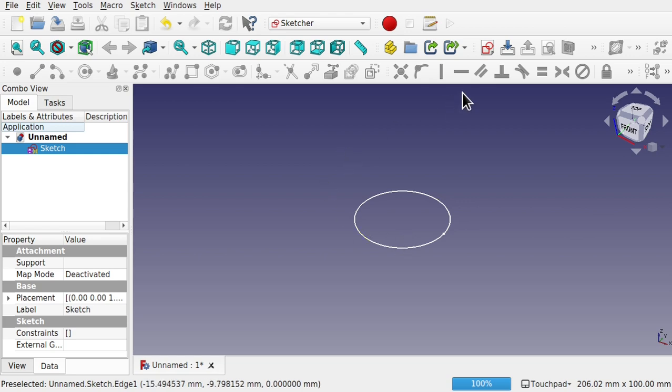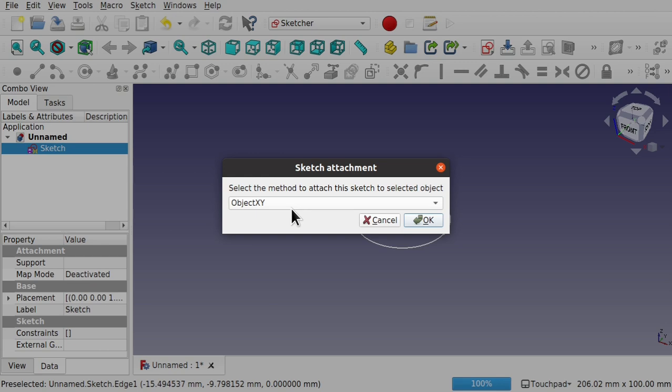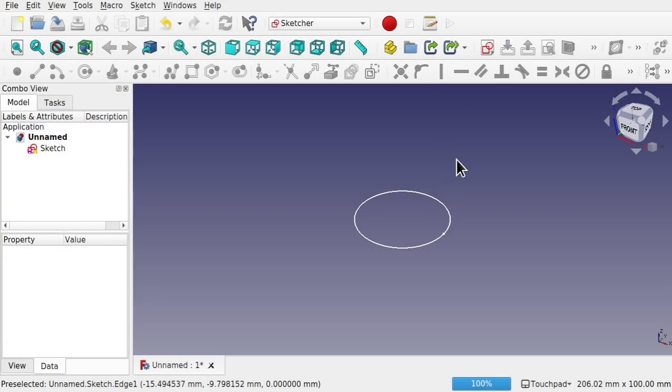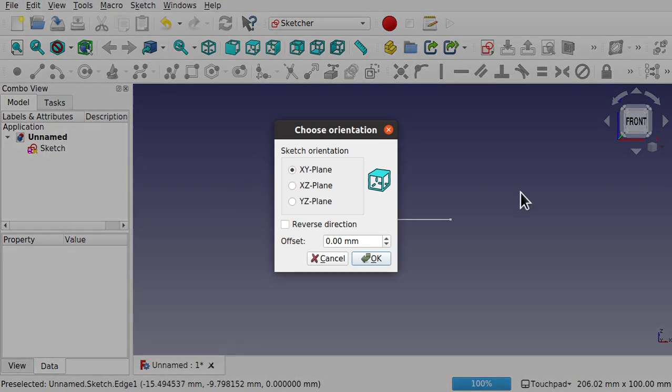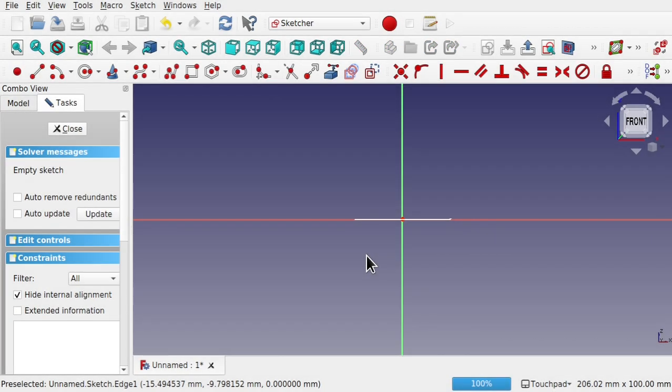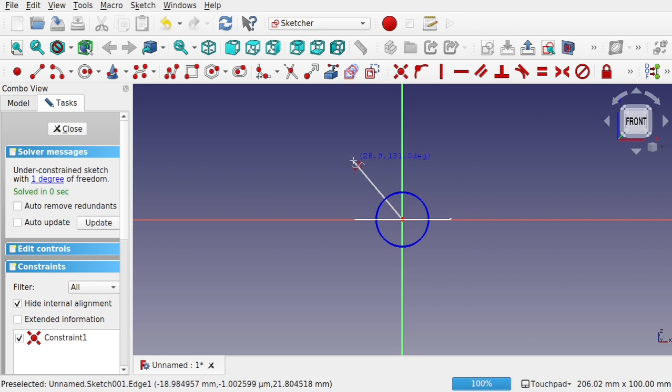We also need a path. So I'm going to create a sketch again. And I'm going to do it on the front. Press sketch on there. And we're looking at the ZX plane. I'm using my handler down the bottom. ZX plane, which is this one here. XZ plane, ZX plane, same thing. Okay. And we're going to place some kind of path in here.